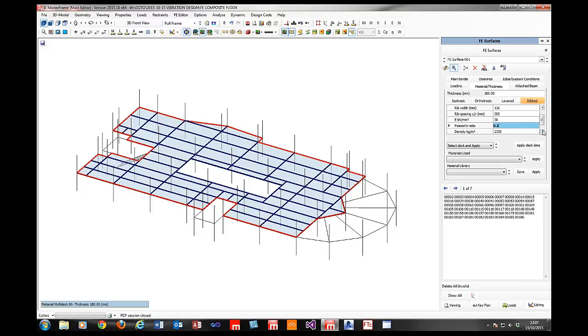You might wonder, well, that's an unusually high value of E for concrete, and that's because we are using the dynamic modulus for the concrete, and that's specifically mentioned in the SCI P354 in section 6. It talks about using this dynamic modulus of elasticity and then the equivalent G value, shear modulus value, subject to the Poisson's ratio from that, and that's set on this surface.